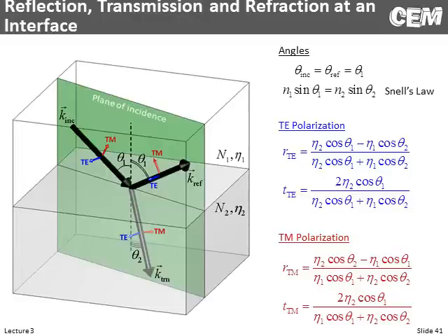As we came in at a larger and larger angle, more and more reflected. So that appears in these equations. And also, the amount of reflection we get has to do with the change in impedances. If we had the same impedance on either side of the interface, there would be no reflections. So we can conclude that it's a change in impedance that really causes reflections.